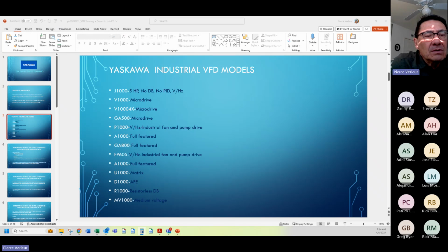So if I multiply that number by the efficiency of the drive, which for the V1000 is about 0.03 on the worst day, you get 560 watts of energy. That's five 100-watt incandescent light bulbs. Ever put your hand on an incandescent light bulb? It's not a pleasant experience. So you still have a lot of energy, but 500 watts, it's doable to dissipate that in a NEMA 4X environment.